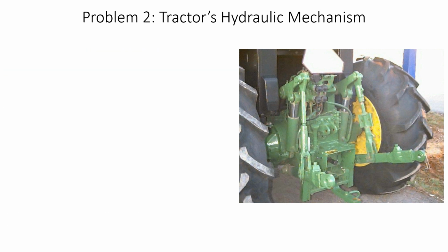The very first step that I'll take is to try to draw a schematic illustration on top of this actual diagram. The aim is to reveal the mechanism through line drawing. So I'm going to start from a node over here. This node, you can see, is kind of a ground node. So I'll indicate something like this. And then you can obviously see that the link which is connected to this ground link has got 1, 2, and 3 nodes connected to it. So it is not a binary link, it is a ternary link.